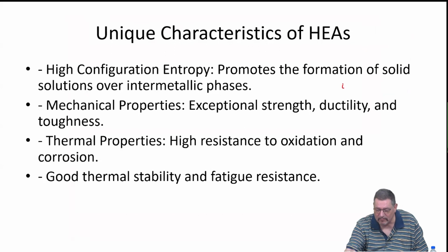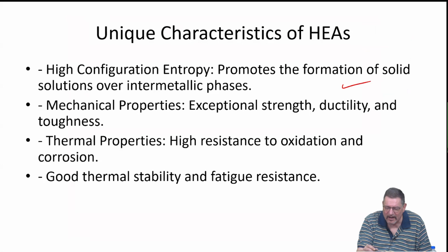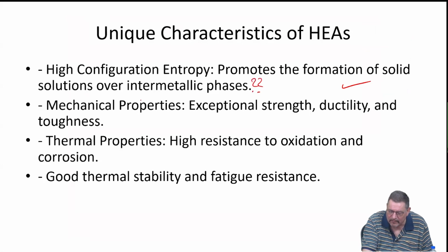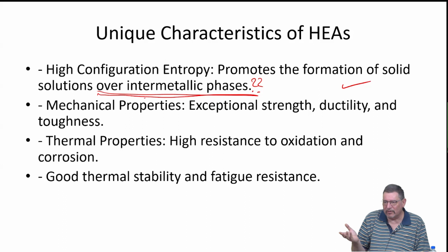So this is obviously high configurational entropy, which promotes formation of solid solutions over intermetallic phases. I would question mark this. Why do I question mark this? Because intermetallic phases often have very high enthalpies of formation. And so you need to have a very large term, temperature times entropy S, to beat the formation enthalpy of intermetallic phases. Temperature is limited by the melting temperature, so you cannot go up higher than the melting temperature, then you will not have a crystalline phase.